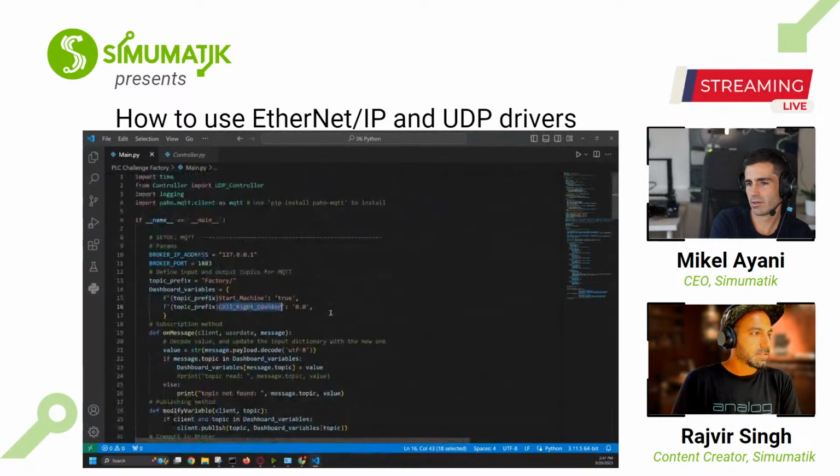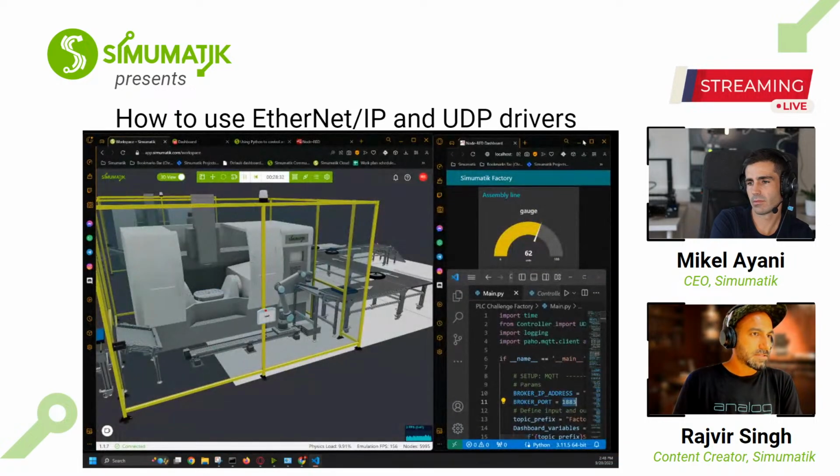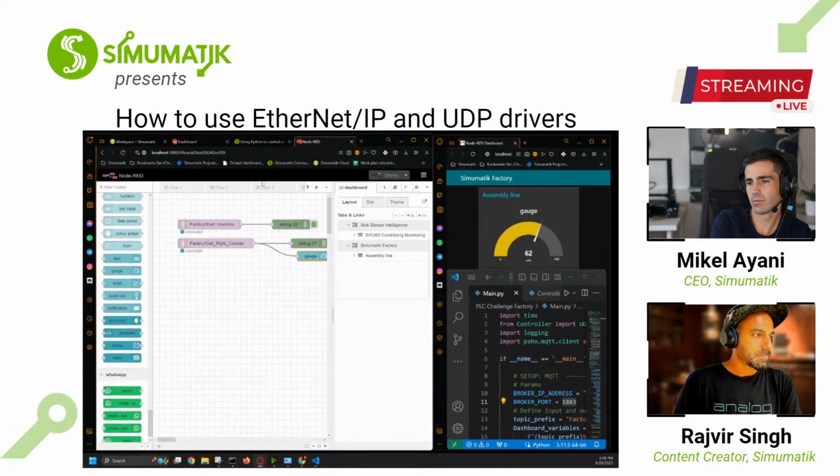So now if you see the Python script, if I go to the top, here is where you define the broker address. So right now, my broker is running in my computer. So you see this localhost address, 127.0.0.1, and that's the port address. And this is the same address I take in my Node-RED. So this is my Node-RED flow. And if you see this topic, factory start machine, factory cell write counter.